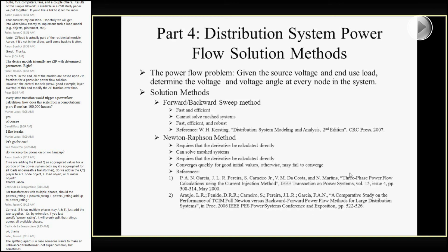If we get into more detail of how the Powerflow solver inside GridLAB-D works, it's predominantly composed of two different methods of finding the solution to the Powerflow. We use what's known as the forward-backward sweep method and the Newton-Raphson current injection method. Basically, forward-backward sweep is very much fundamental circuit analysis, but it's quick, efficient, and works very nicely. The method is outlined in William Kersting's book, Distribution System Modeling and Analysis. That's the book I referred to earlier. I couldn't remember the exact title. Very nice book for distribution system analysis, especially for this particular method.